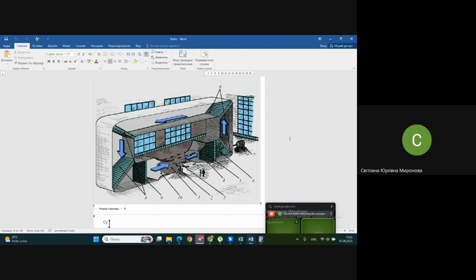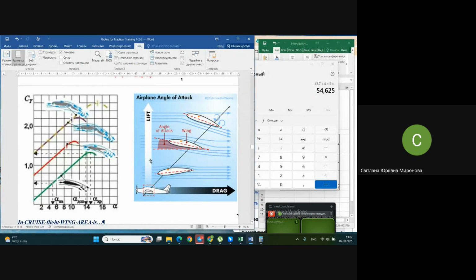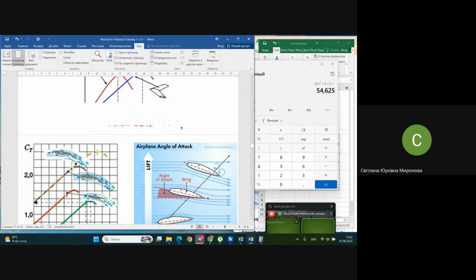So this characteristic may be determined in case you're able to do a model. But to do a model, you need to know geometry. And we came back again to the same circle. We don't know geometry yet. We don't know sizes. We can't estimate properly the value of this coefficient of lift. So we take some average value approximately for the first calculation. Let it be 1, for instance. Let it be 1 for our very first calculation.